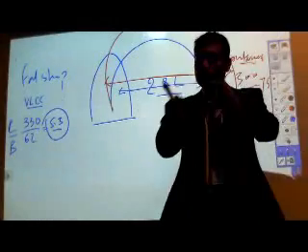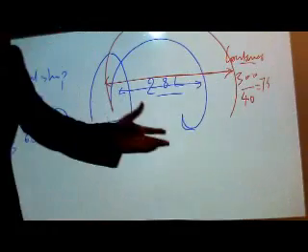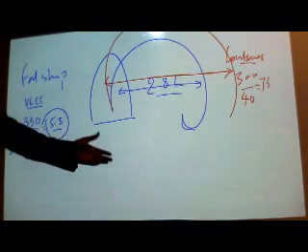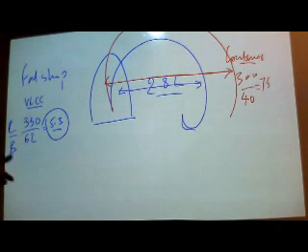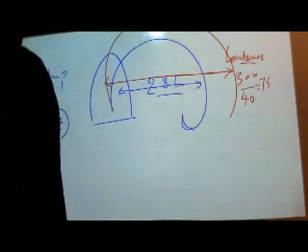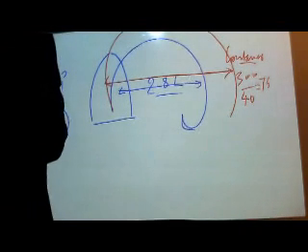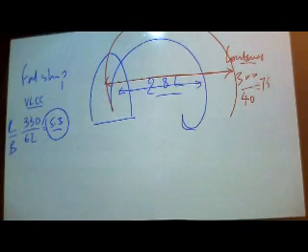Well, on an LNG ship, you can yourself decide what kind of ship that would be, by length to breadth ratio. Now you know how to play with it. Where does it fall? Is the length to breadth ratio very high? If the length to breadth ratio of the vessel that you will be on is very high, you will yourself know that turning of this vessel is going to be difficult, but steering of this vessel in one direction will be easier. But if the length to breadth ratio is very low, steering will be difficult to maintain its heading, but it will turn really well.